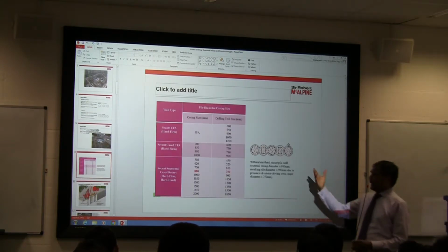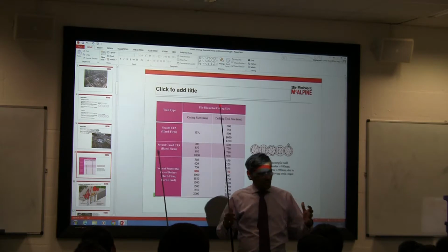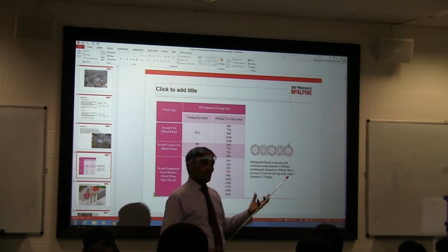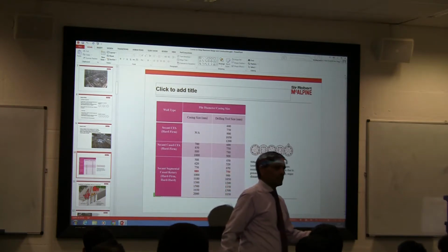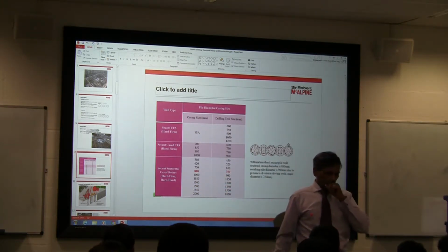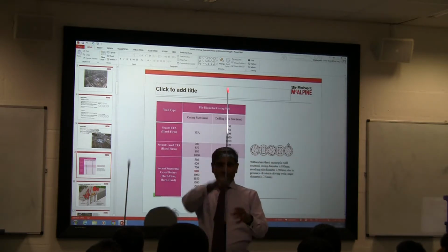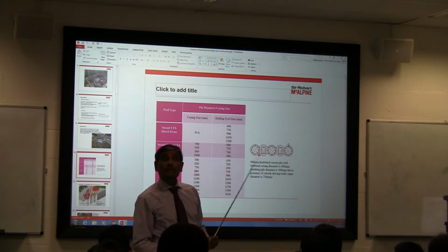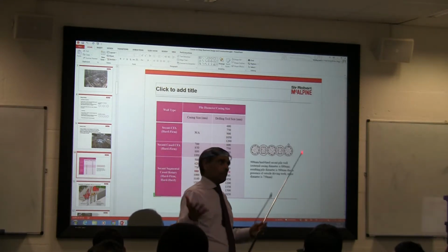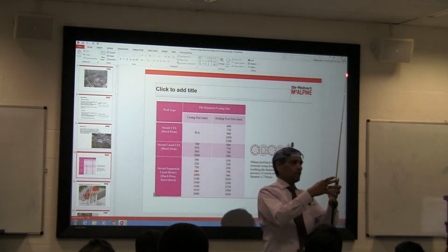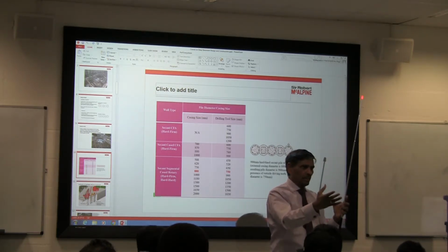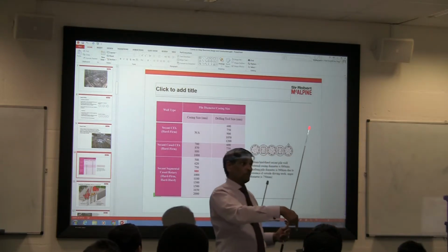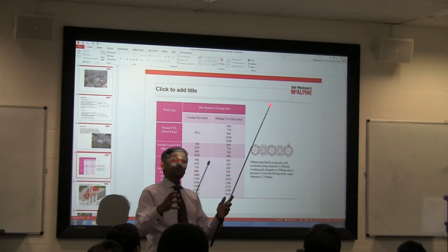So this gives you some guidelines in terms of the diameter of the casing. Sometimes we have to put temporary casing, sometimes we have permanent casing. Why do we need a temporary casing? When I'm doing the piling, can I just drill the hole? Absolutely right, to maintain the pile and stop the ground collapsing. As soon as you make a hole, imagine if it is gravel or sand, what will happen? Simply, it will come in. So there is no way you can say that I am going to pour concrete and it's going to carry load. So you've got to put in a temporary casing.